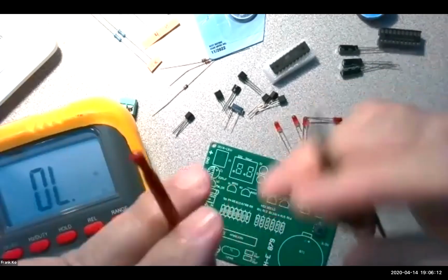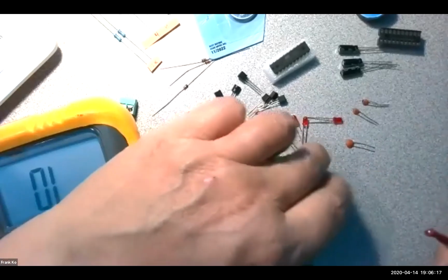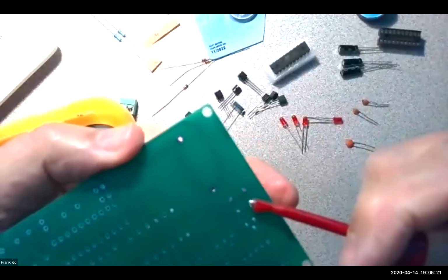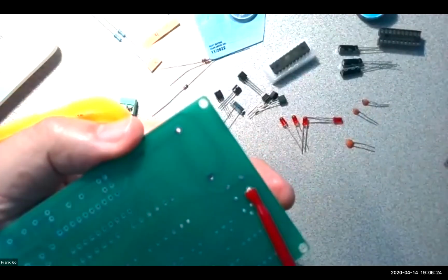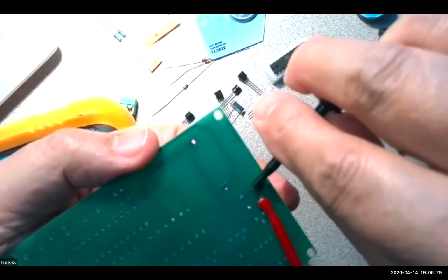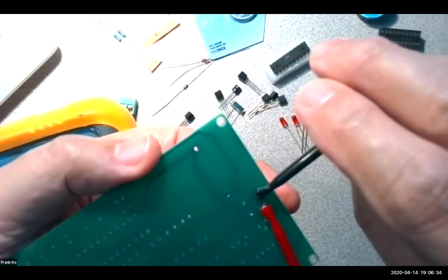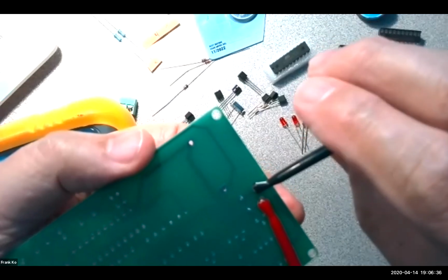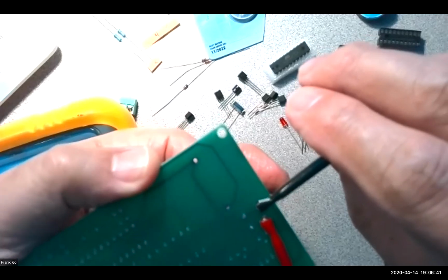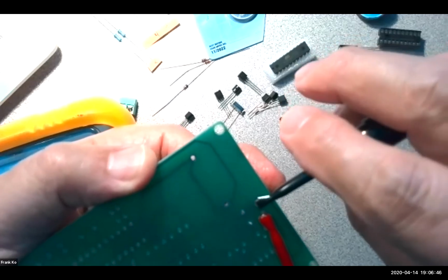So that means I've got continuity on these 2 pins. If I go to this switch, and I'm not sure if I have enough on here to grab, but maybe if I get lucky. Okay, 1 there and 1 there. Maybe if I put my hook this way. And I go to press the switch. No press, no continuity. Press, continuity. That's the way it should be.